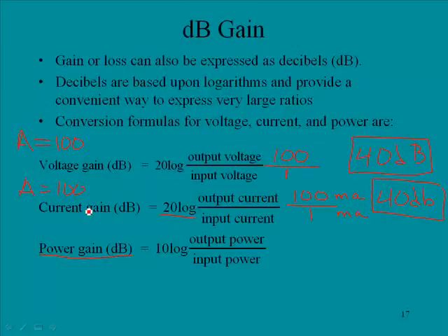So what we could do, if we pretended that this was the same amplifier, we want to evaluate the power for this amp, and we say, well, we had 100 volts of output, we had 100 milliamps of output, so the 100 times 100 milliamps would represent the total power.